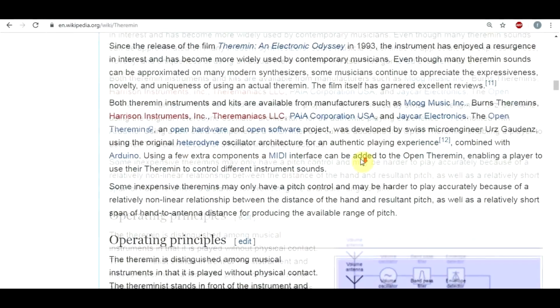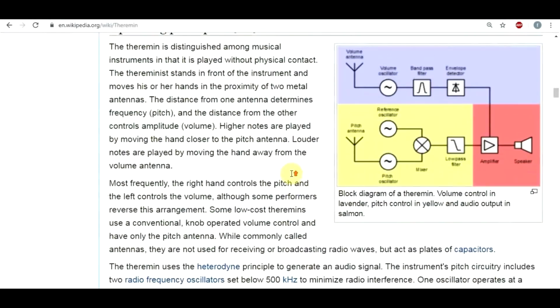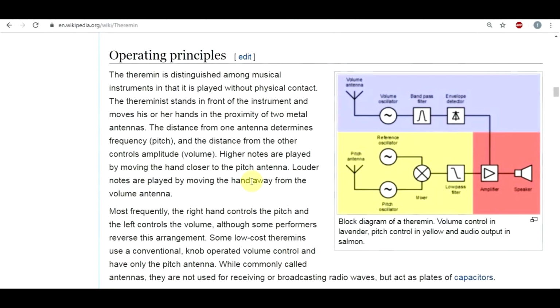So, how does it work? Well, you may have noticed by the sound that it produces that it can produce a single frequency sound that has a variable volume. And this is exactly what we can see in this block diagram. The circuit has a part that generates a signal to control the volume, and the circuit has a part that generates the audio frequency that we can actually hear. And then you need to combine the two. So let's see how we can do this.